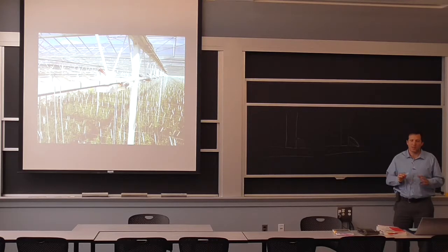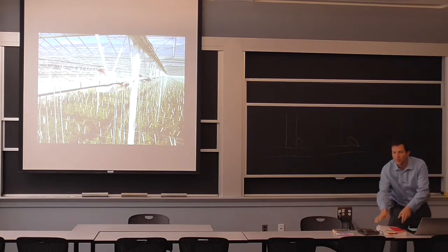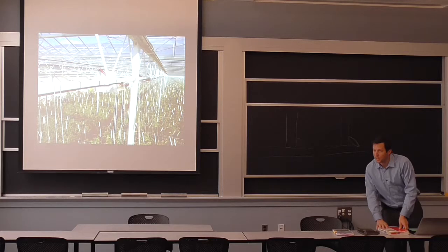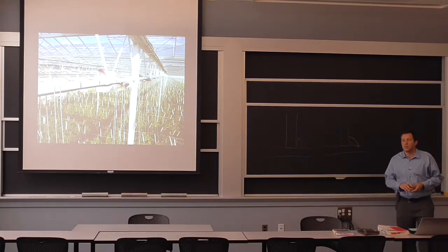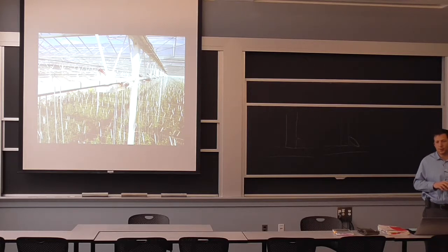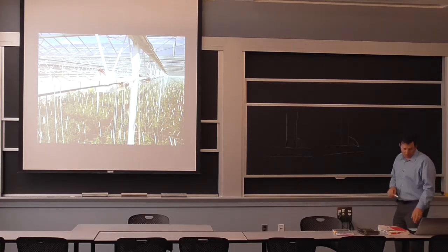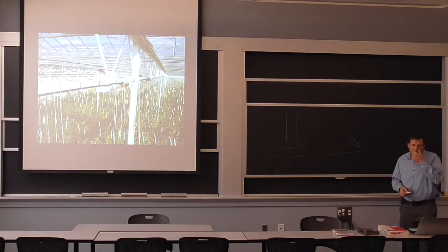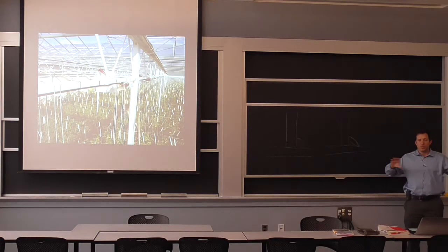And the basic story there with roof joists is they are not required to meet this code. They're not inspected by certified welding inspectors. They do have welding specifications, and it's written down in a somewhat similar way. They'll say you don't want lack of fusion, but they don't have the criteria on the surface that we've talked about here. These are not included in that spec. So it's more of a performance-based spec where they do what they do with quality control.